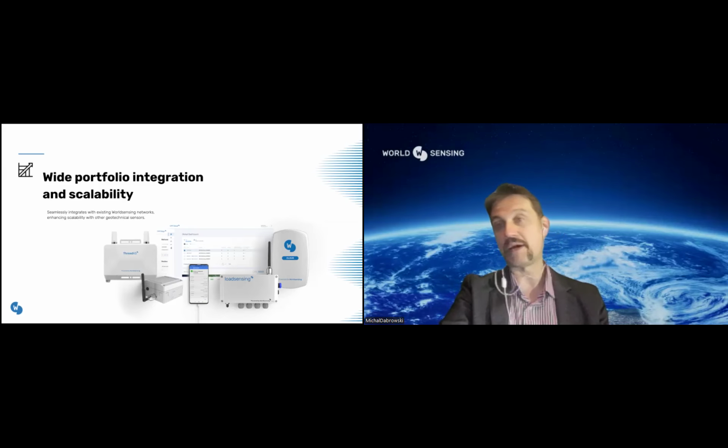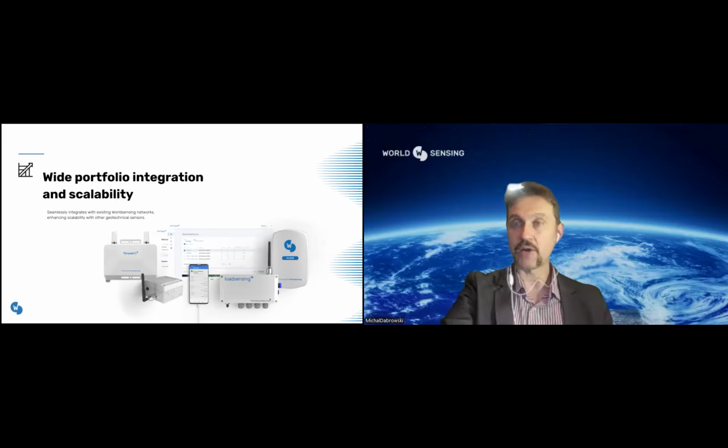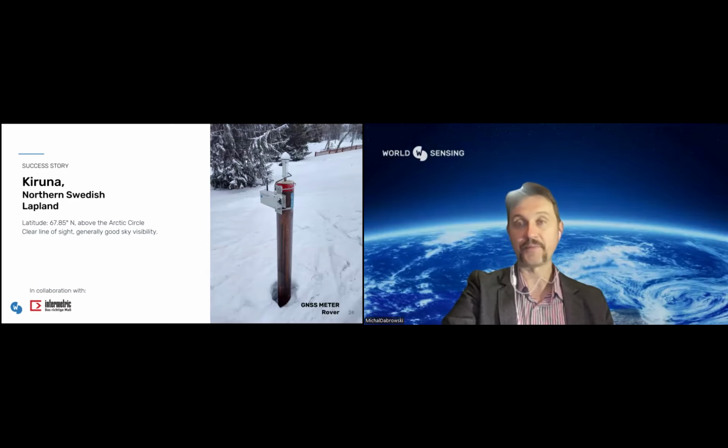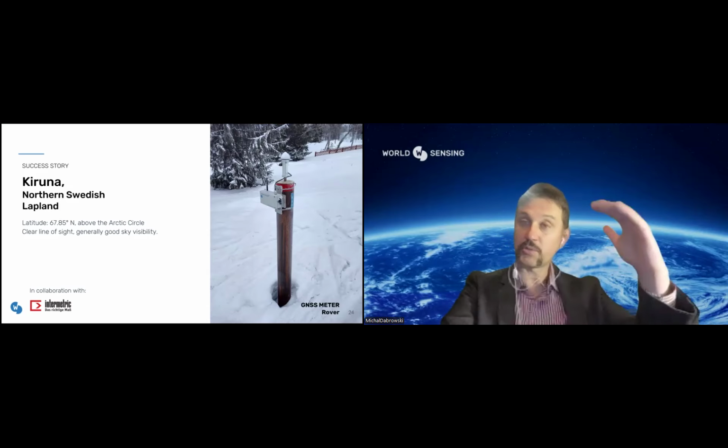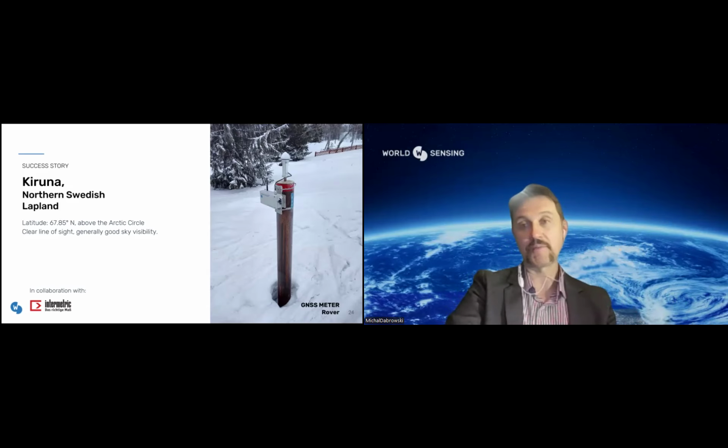You can have that combined with the extensometer, or you can have that combined with the in-place inclinometer. That will basically allow you to gain your profile from your IPI a lot more accurately, or basically have that being deployed in a completely different manner, from the top, from the bottom, from the top to the bottom, and on the top you would gain your point of reference.